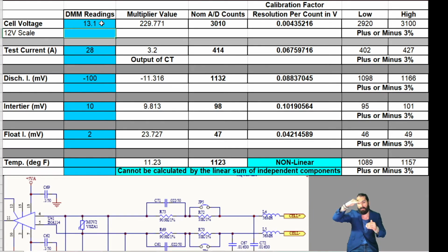So as the voltage moves up, it'll get scaled and maxed out. This is very vital to understand within monitoring circuits, because if you don't apply these fundamental principles to the multiplication factor, the divider circuitry, and the analog to digital circuitry, you'll have no idea how to troubleshoot these monitoring circuits effectively.